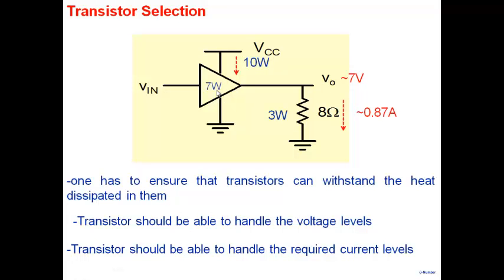See, at the previous stages, for example at the gain stage, the currents are low. The voltages may not be as high. Power is obviously not that high. You don't have to worry too much in the previous stage. But at the output stage, the current is the highest, because that's where you have to deliver power. The dissipation is highest. So you have to start worrying about these things here.